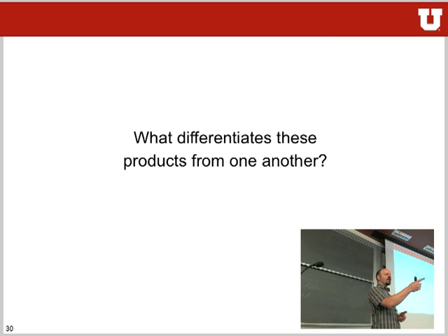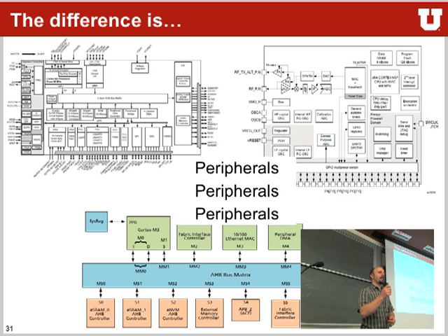Proprietary. But what is proprietary? The core is open. What their chips do. Sorry? In a lot of cases, the on-chip peripherals. Yes. Peripherals, peripherals, peripherals. And that's where all these chips differ. They have all the same core. It's all an ARM Cortex-M3 core. They run at about the same speed. They draw probably significantly different amounts of power depending on what technology they are using. But the big difference in all these chips is peripherals.